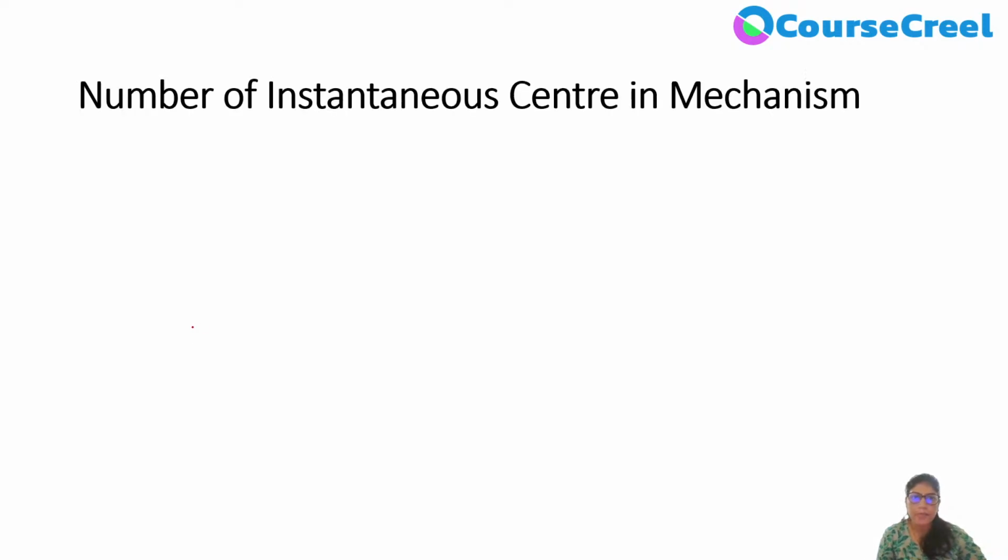So it is the instantaneous center method. Look, what is an instantaneous center? Suppose we have any link, okay, and suppose we talk about a point here on this link. It is in continuous rotation. In that case, that particular point is rotating about a point. Okay, so that point about which that link is rotating is called the instantaneous center. Okay, so we will consider it as a center. Okay, so how to find its location, I will discuss now.